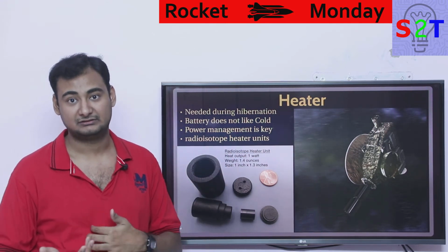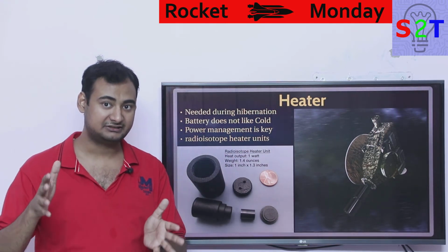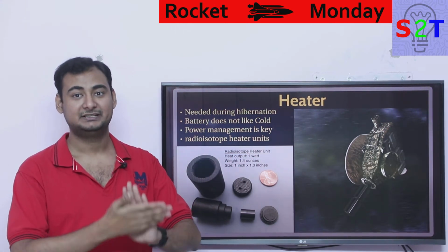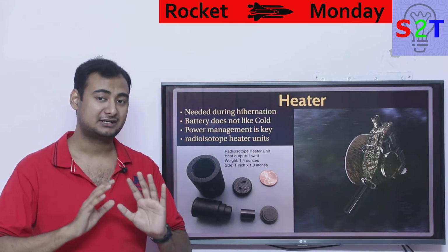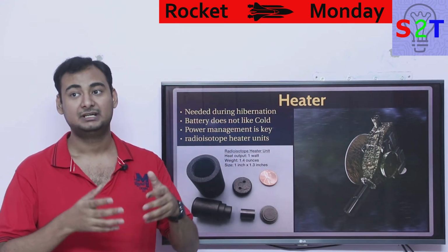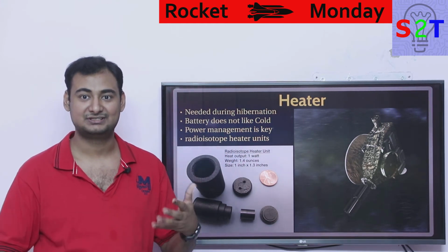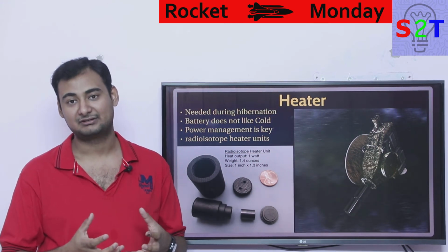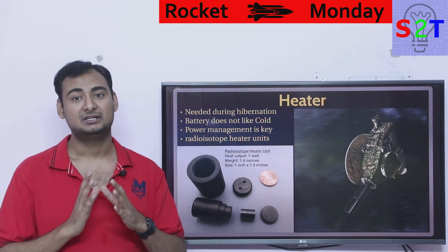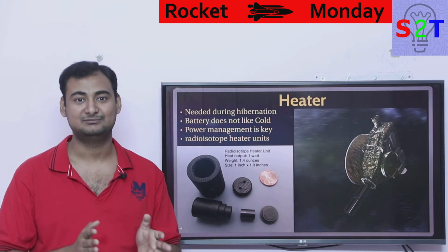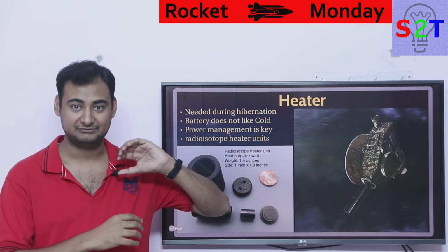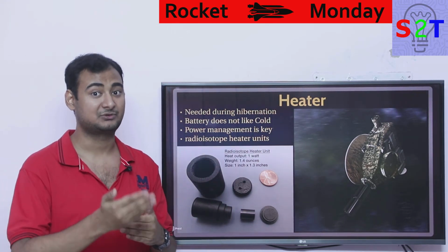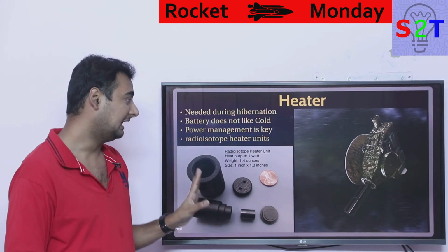Generally, let's say in the case of Saturn missions, you had liquid oxygen in the tanks, and because our sun is not very bright in X-ray or gamma rays, the white paint and the material coating used stopped it from heating the fluid. Consequence: the liquid oxygen ended up freezing solid, so they had to add heaters there to make sure it's never frozen solid. That was also an issue with the SpaceX Falcon 9 Block 5 Heavy edition, where if it was sent very far off, the fluid may freeze simply because evaporation is also happening. So we have to do power management.